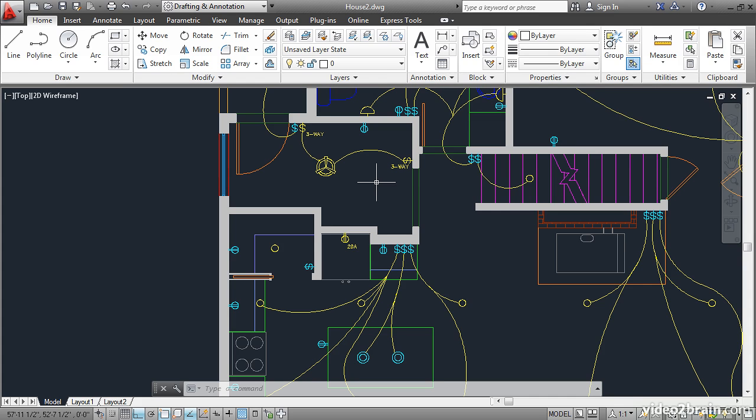In this lesson, you will learn how to override general properties with specific colors, line types, and/or line weights. You'll also learn how to restore overridden properties back to their default by layer state. In addition, you will learn how to change objects' layer assignments using both properties and the layer drop-down menu.